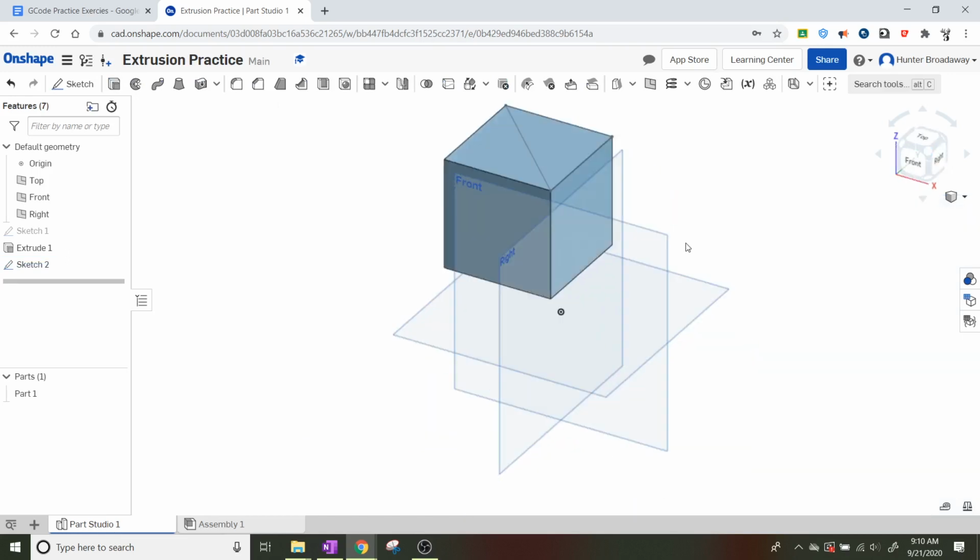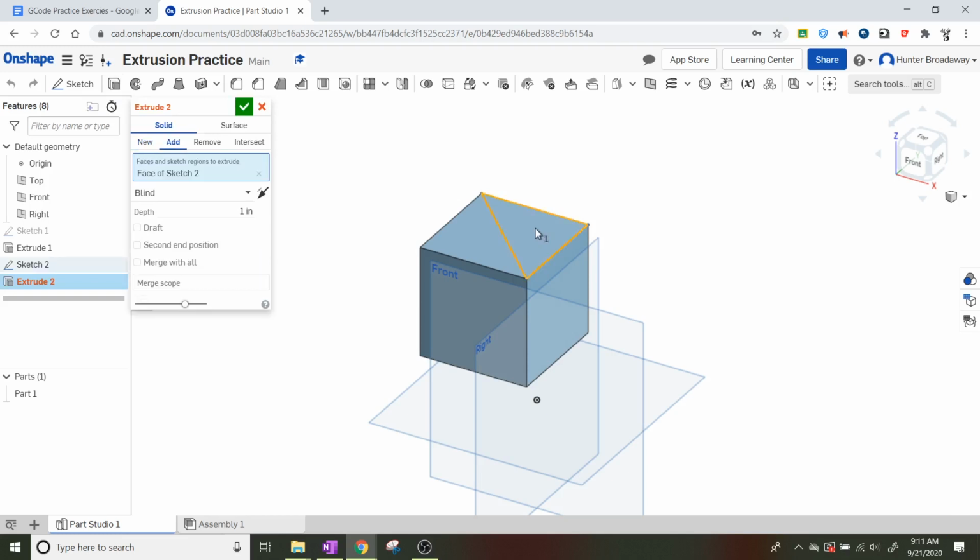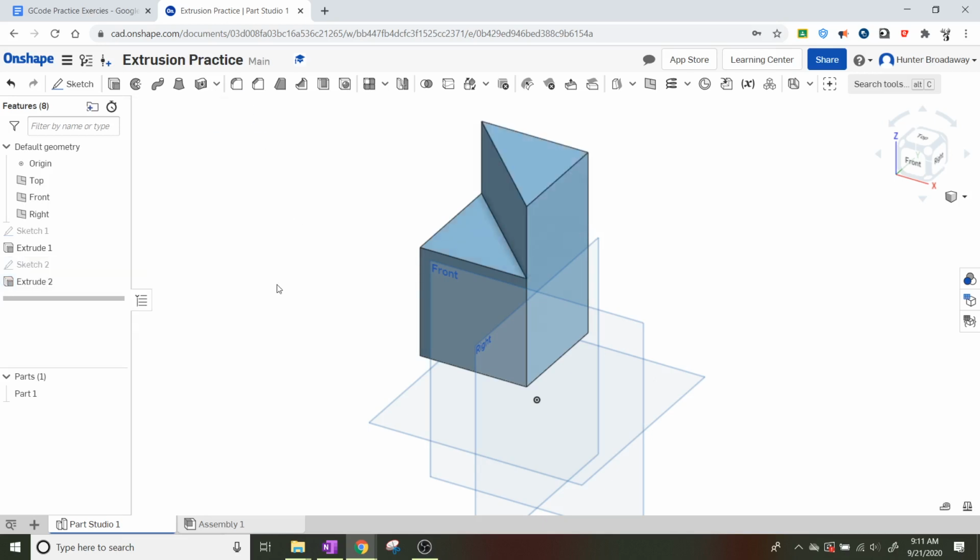There we go. Okay. Now, when I click extrude, it's not going to extrude a square. It's going to have that shape that I could actually extrude from, and I can make a shape on top of it. So I can add to this shape that I already created previously. This is called additive modeling, and it's additive because we're adding shapes to it. Okay, this isn't meant to be super rocket science. I'm going to make the extrusion, I don't know, let's make it 2 units high. So I'm going to hit that, and then I'm going to hit the green check mark.